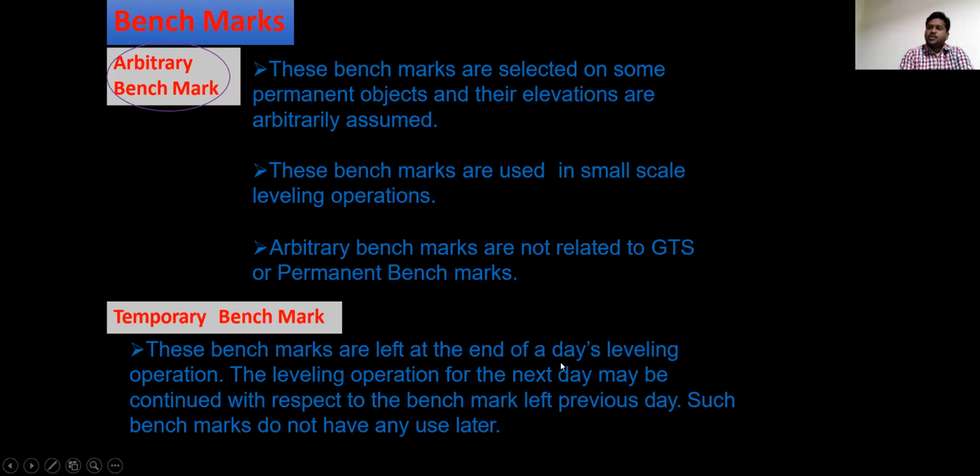So whatever benchmark you are taking will end at the end of that particular day of survey. The leveling operation for the next day may be continued with respect to the benchmark left the previous day. So to the benchmark you left the previous day, we again take one more benchmark with reference to yesterday's benchmark and conduct the survey. That is called temporary benchmark.